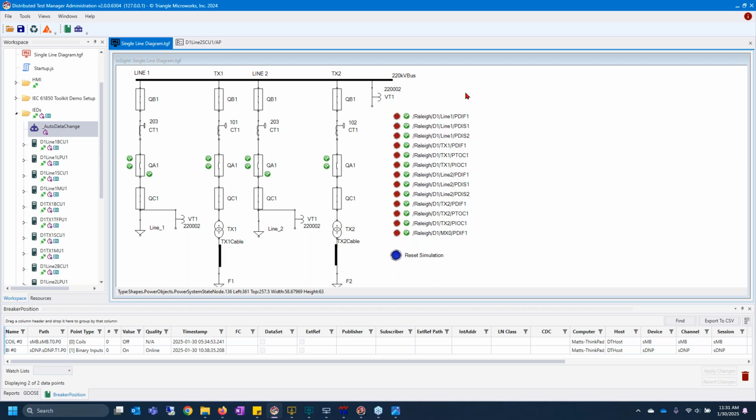And what should happen in that case is the breaker should be opened, right? There's a fault on the line, we should open it up. Sometimes just by simply opening the breaker and closing the breaker, the fault is taken care of. And in that case, the breaker can then just close back and remain closed and everything is back to its nominal state. Other times, if it closes back and the fault's still there, it needs to open again and then signal someone to come actually take a look at what's causing this fault.